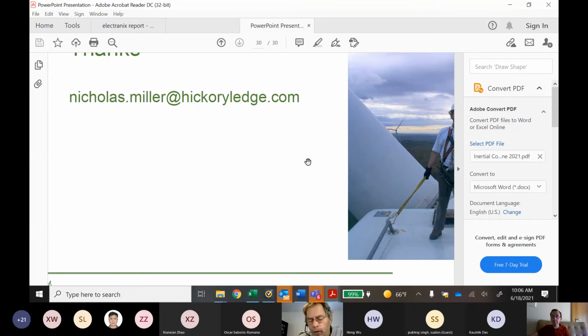So this is a feature that will make the system run better and increase the optionality for providing primary frequency response. The Hydro-Quebec example really drives the point home. Hydro-Quebec has intrinsically lots of primary frequency response capability. It's hydro dominant, but the hydro plants are slow. So in that situation, using the turbines to buy time for a resource that's already there makes tremendous economic sense.